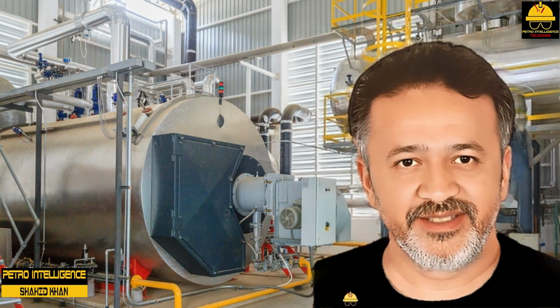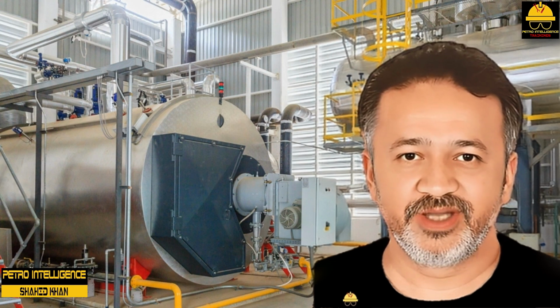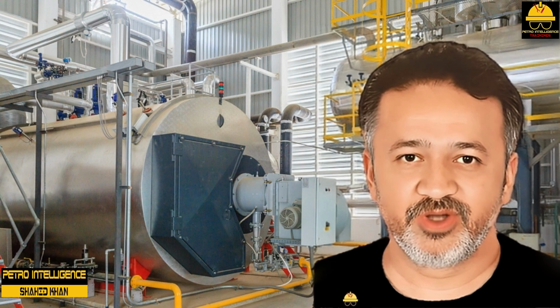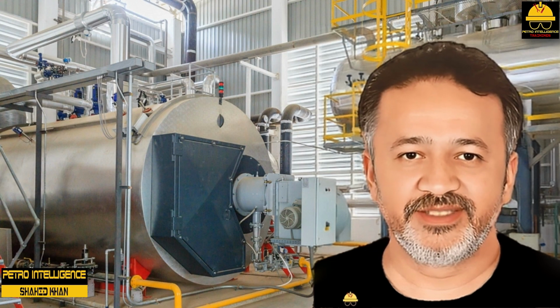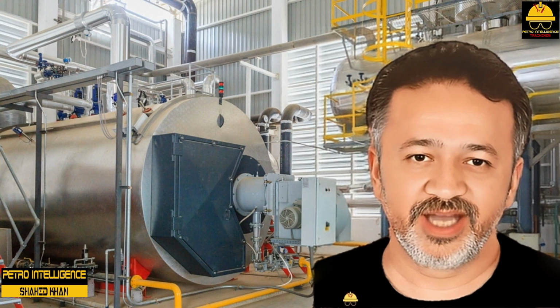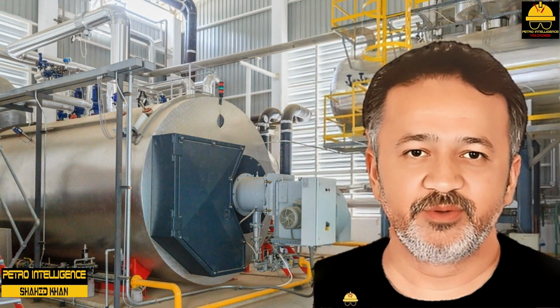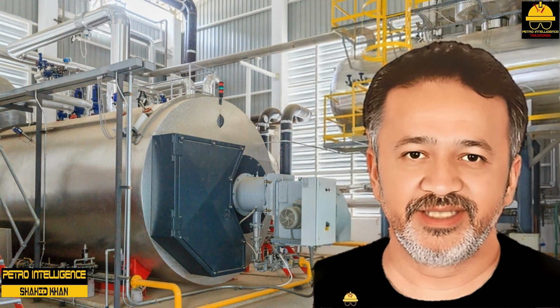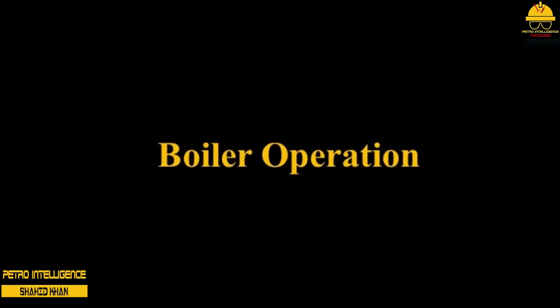Some plant processes cannot tolerate high temperatures. The process of cooling the superheated steam is referred to as desuperheating. During the desuperheating process, part of the superheated steam is returned to the steam drum. The cooler liquid in the steam drum removes heat from the superheated steam and allows it to be used in specific plant processes.